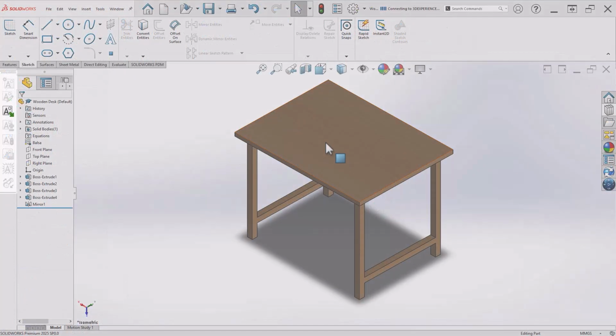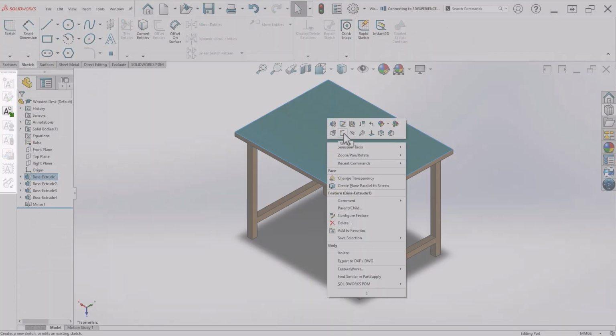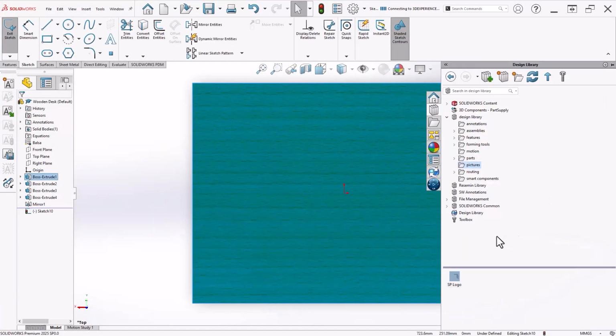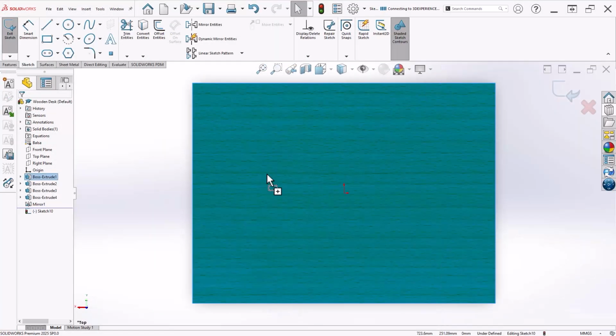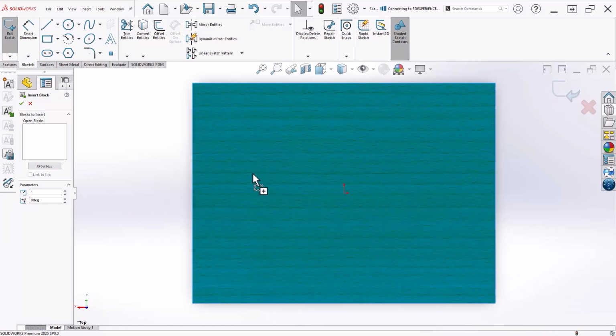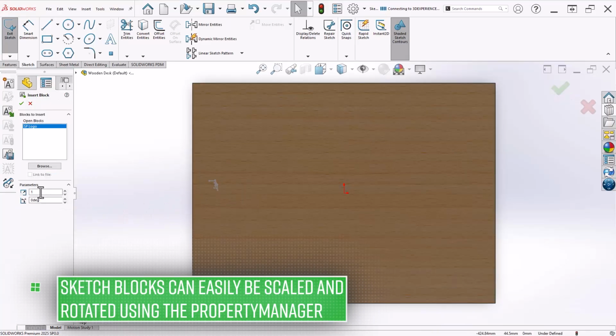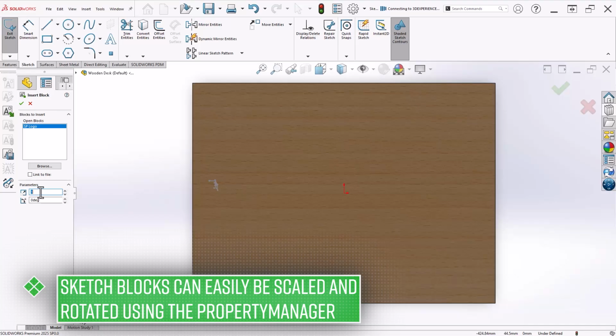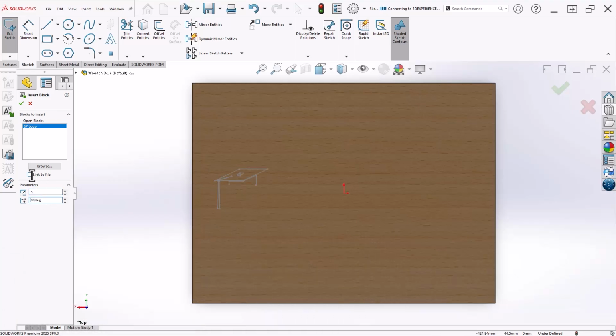Making a block is easy using the Sketch Block toolbar. We can use a block to add all entities together for reuse in another document, or we could group them to allow for more realistic movement. A good example of using sketch blocks is to save complex sketches so they move together and can be reused.